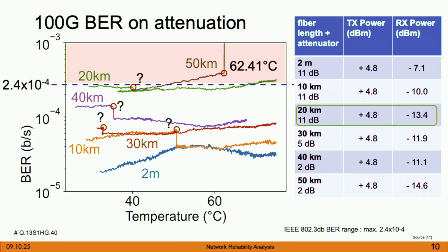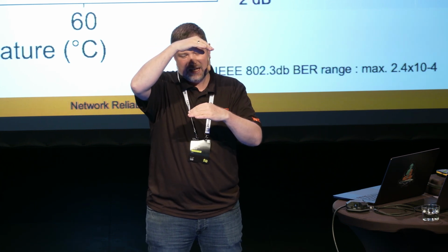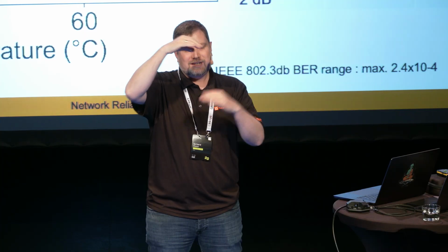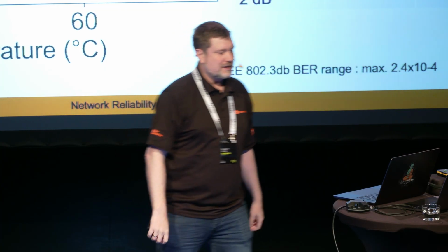To explain it briefly, usually you have, in the ideal world, your rectangle signal. So if you have a high signal and a low signal, you can assign ones and zeros, and that is how it works with direct detection transceivers. And if you have an oscilloscope and you go as fast as the oscilloscope in your relative velocity as your bandwidth, you end up seeing also a rectangle, because everything is drawn on this display. This is the ideal world. Realistically, you have curves, obviously, and if you join all these curves together, you get to see an eye. That is why it is called an eye diagram.